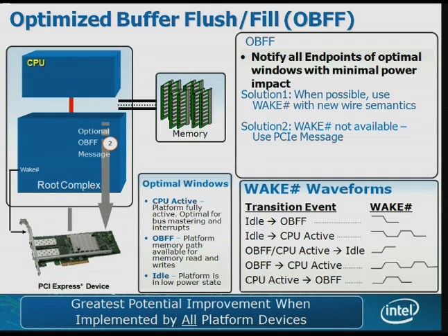This feature would redefine the WAKE signal that was usually driven from the device to the system. In this case, since it's an open drain type of signal, it will be both, depending on the context: the platform telling the devices what the platform state is, and devices also requiring attention from the system.